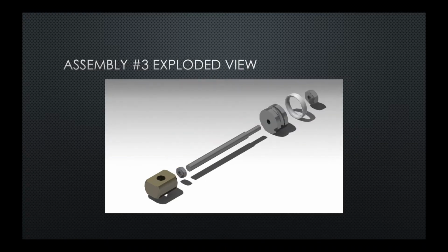Here in the exploded view, we see the different parts of the assembly, with the piston head and its nylon seal creating a solid wall between the 2 sides of the cylinder, creating a difference in pressure that moves the piston up and down the cylinder, with the motion being carried by the rod down onto the crankshaft by the crankshaft bearing.